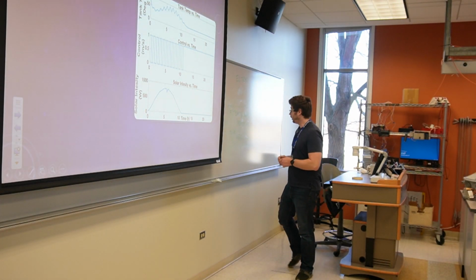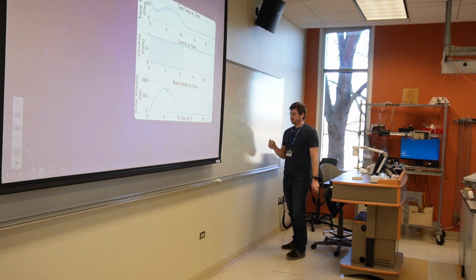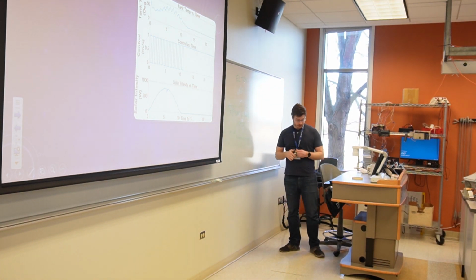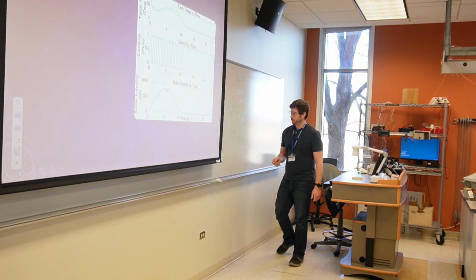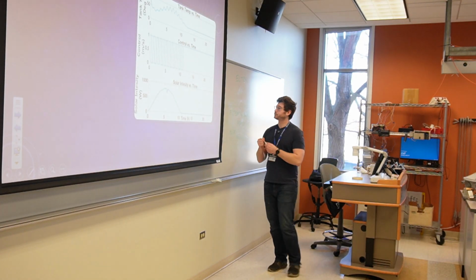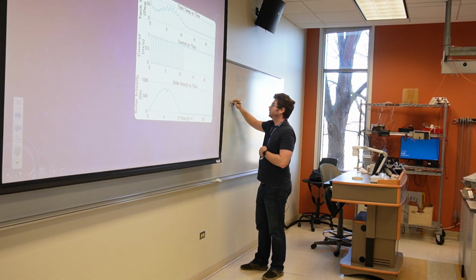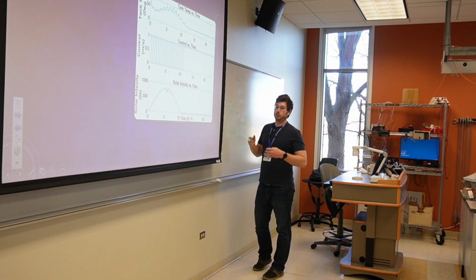Okay, one pitfall of bang-bang temperature control really happens when we're trying to use relays as our control element. As we approach our set point, weird things happen. Remember I told you guys that when we have a temperature sensor, there's some amount of noise on that device, right?